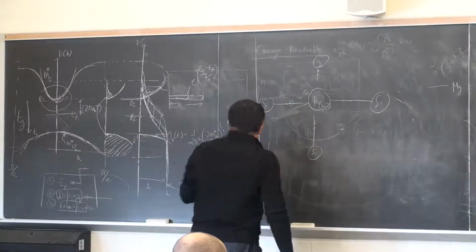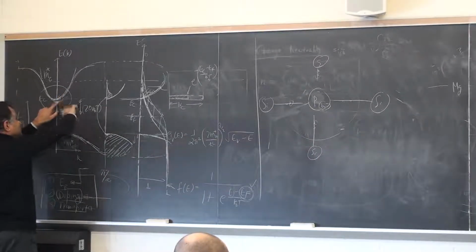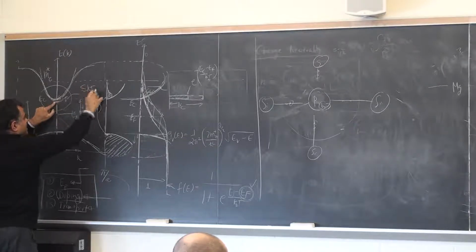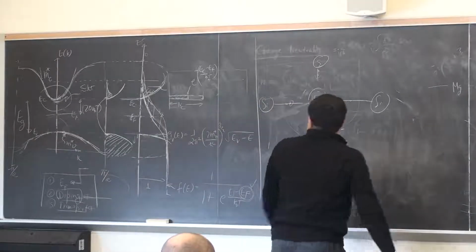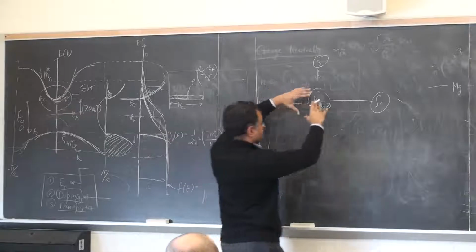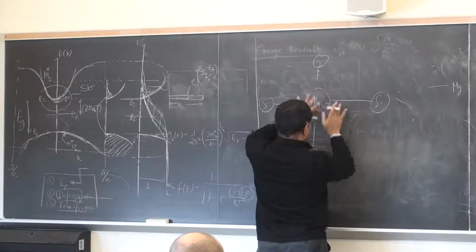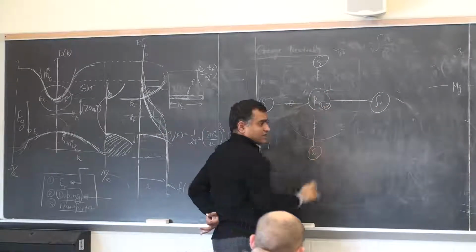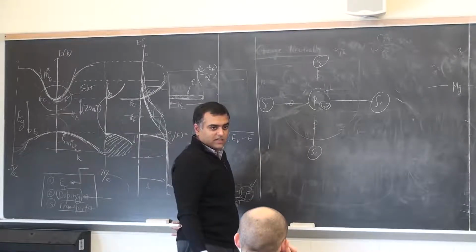But if the energy state is very close to the minimum of the conduction band, such that the ionization energy is of the order of or less than kT, then at room temperature that thing will be ionized. It will get out into the band. Once that electron becomes delocalized, it is free to move around in the crystal, and this phosphorus atom gets positively charged. It was neutral earlier, so it has lost an electron.